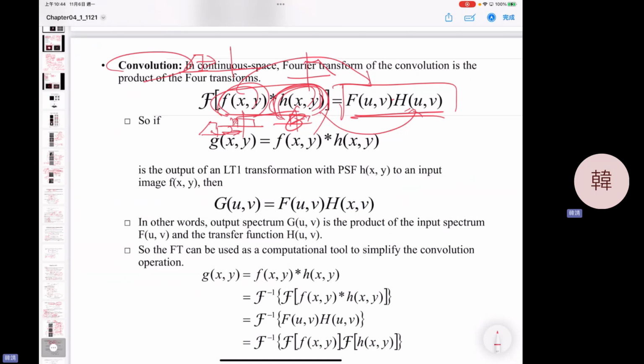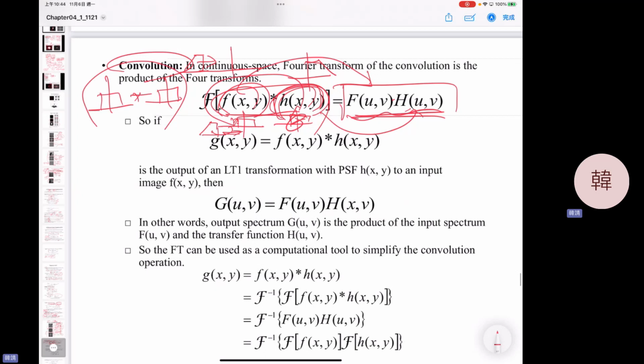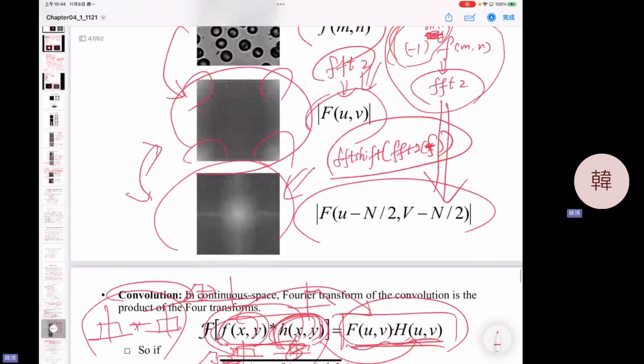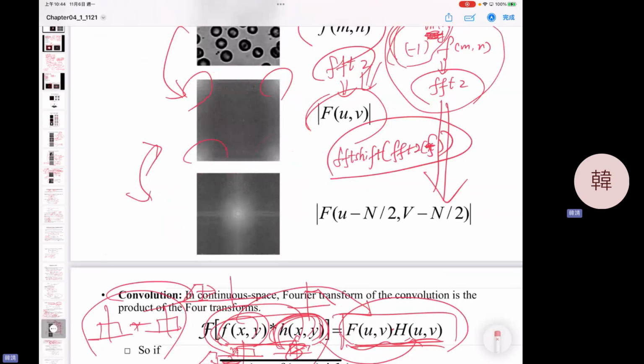With convolution, you cannot imagine what the result is. For example, you know a rectangle convolved with a rectangle in the time domain? What's the result? It becomes a triangle. But if we look at it in the Fourier domain, it's much easier. You just use multiplication. So we look at this spectrum here, and then we know what our filter design is.